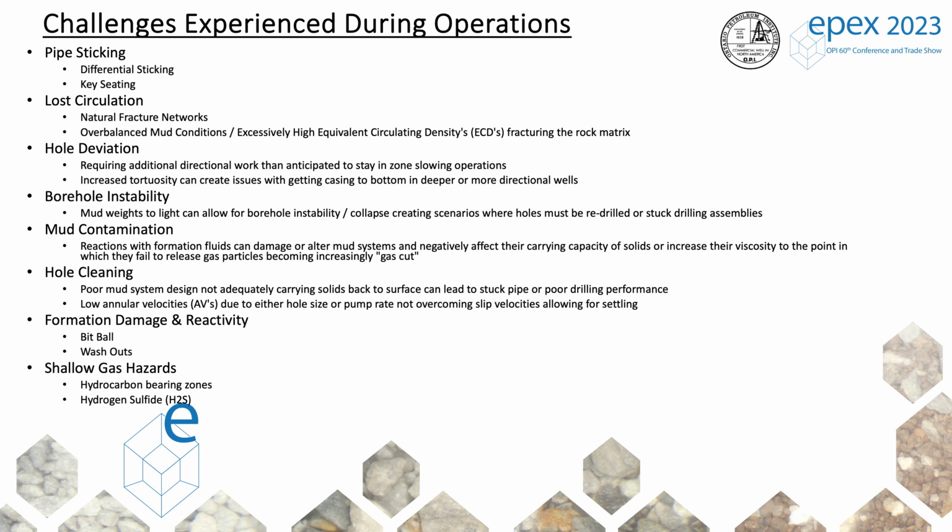Some of the challenges we've seen in our drilling operations are very similar to conventional drilling. Pipe sticking, whether it's differential sticking or key seating, and lost circulation. We see a lot of natural fractures, especially at the top of the salt zone. Overbalanced mud is leading to differential sticking.